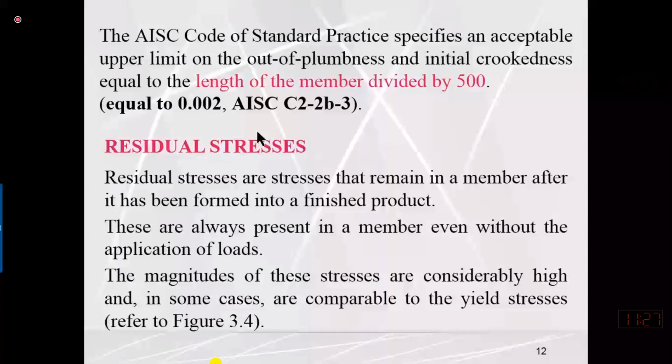It means that the material surrounding the hole that I have punched has undergone stress more than yield stress. If the stress is applied more than yield, I cannot recover all the elastic deformation. Those stresses are permanently stored.